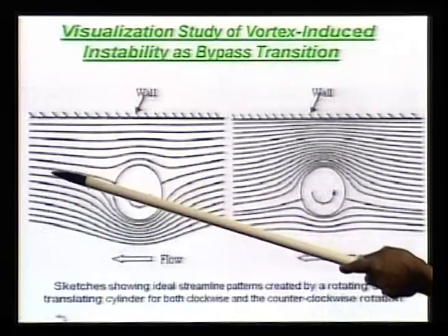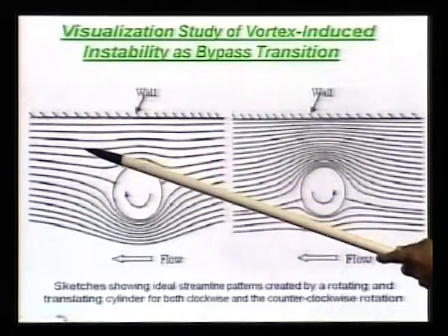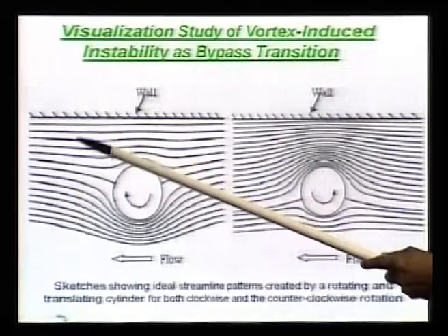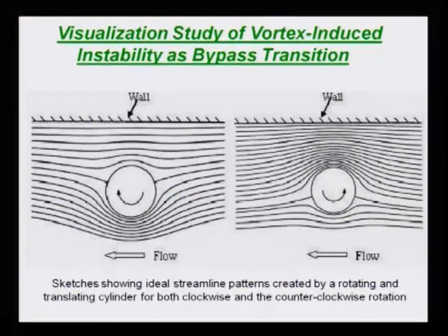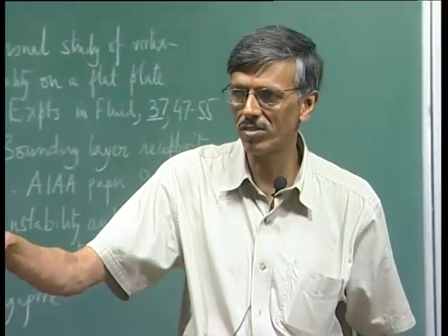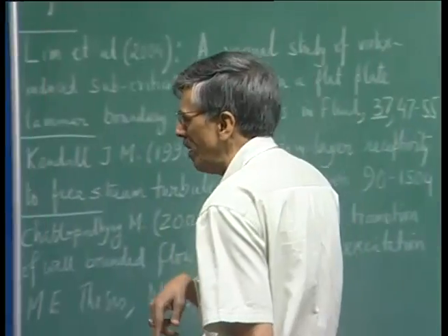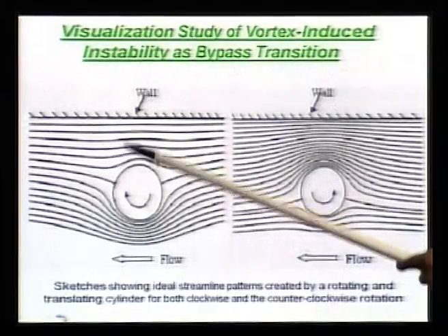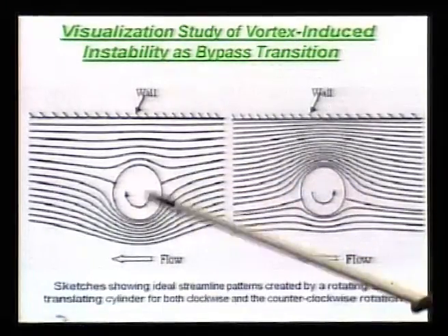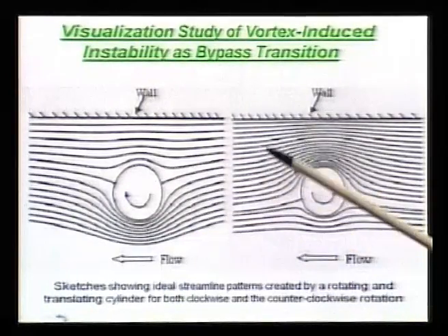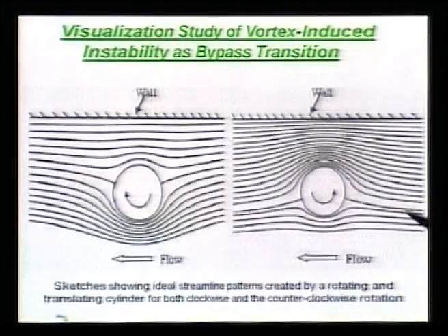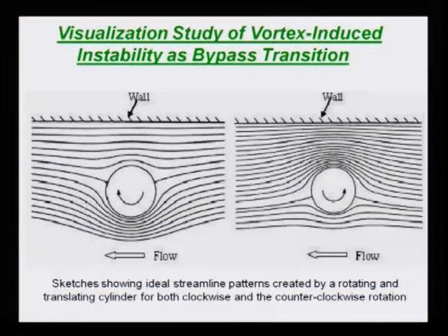because later on again you can see streamlines converge. So, you have a favorable pressure gradient. So, that is what I was telling you about the strategy of avoiding, say, convecting vortices effect, whether you want to go above or below, because the adverse case is a very narrowly focused region, whereas in this case adverse effect is over a large region, and it keeps it all pervading, right. So, this sketch is pretty much revealing that you can understand it.